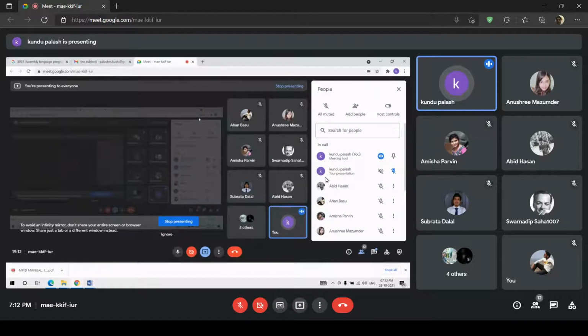You have to understand the serial data communication basics that I have told. The protocol is the asynchronous data communication protocol, not synchronous. And the serial data controller is either a UART, Universal Asynchronous Receiver Transmitter, or it may be a USART, Universal Synchronous Asynchronous Receiver Transmitter. That means some microcontrollers include a serial data communication controller which can perform data communication either asynchronously or synchronously.